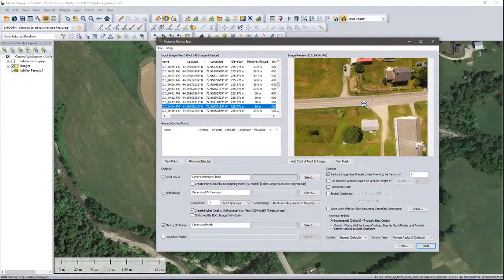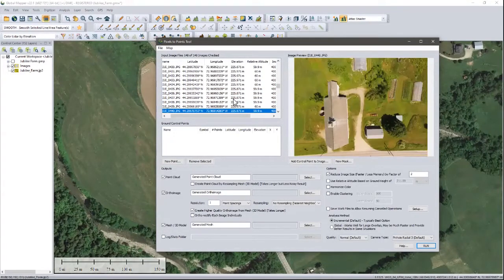If I went to the adjacent flight line, I would see the same building, slightly different perspective here. We're obviously flying back along an adjacent path. So we're seeing the same building from a different vantage point. So when we initiate this process, it will be an analysis of these images that will allow the application to recreate this again in a three-dimensional context.